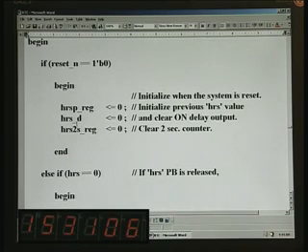We also need a delay output, so as to keep track of that pushing continuously for 2 seconds. So this is what is going to keep track of that, and this is basically derived from the hours push button, right. If you push the hours button in order to set, only then all this comes into play, and the condition for hours is the debounced condition of the push button hours, which is hours, and its previous value is what we earmark as hours p, okay.